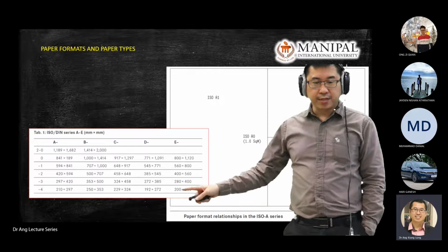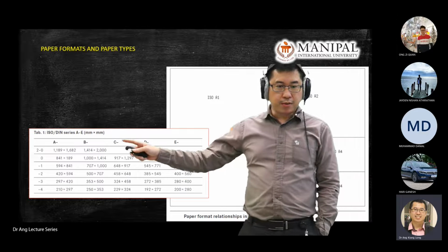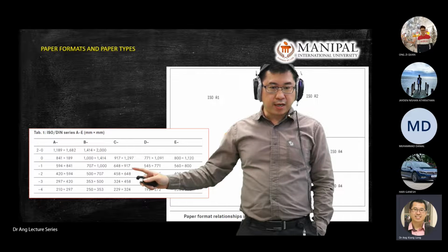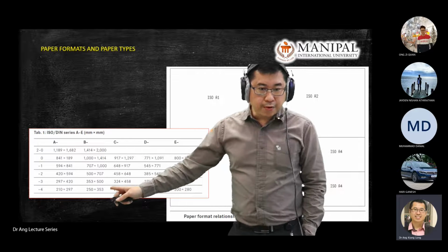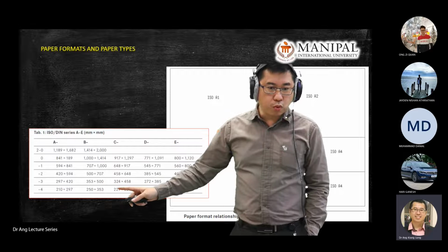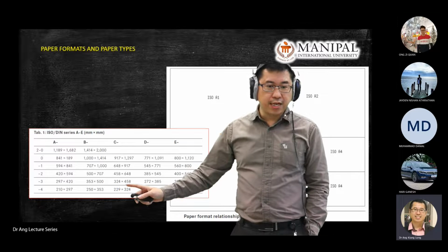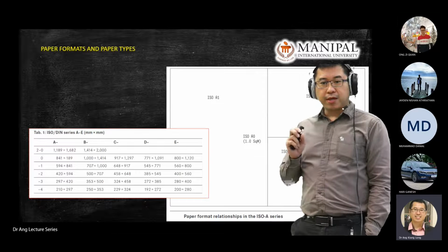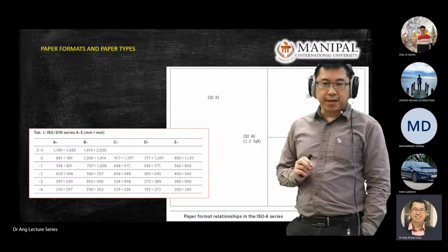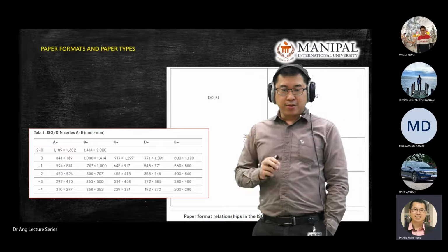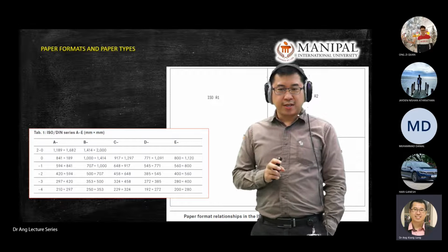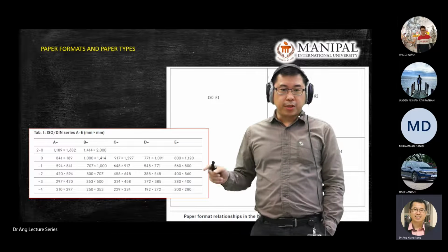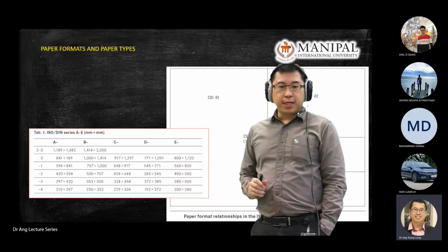Quite standard, right? Quite standard. So this table will tell you ISO standard. So if you go for let's say A4, so the A4 sizes will be 210 times 297. When we talk about technical drawing, we deal with unit in mm. Okay, throughout your drawing or your submission of a report later on, especially when you come to technical drawing, all your unit will be in mm.